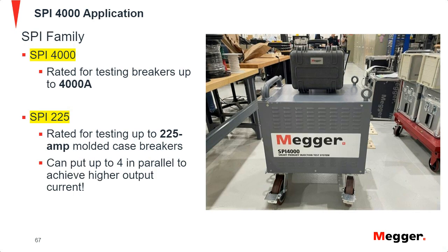So again, the SPI 4000 is part of our SPI family. When we say SPI, we mean Smart Primary Injection. So that's just going to be all software based, right? The SPI 4000 is rated for testing breakers up to 4,000 amps. The 225 is rated for testing breakers up to 225 amps. But those can be put in parallel to get a higher current output if needed, up to 4.